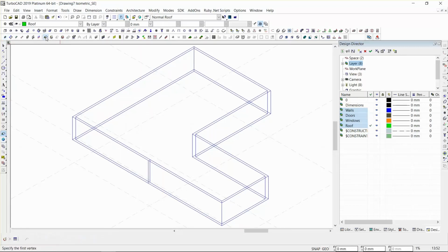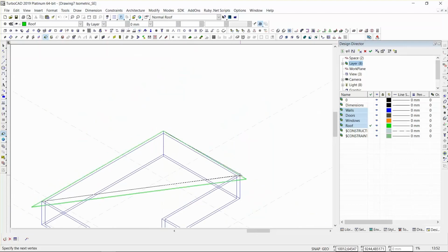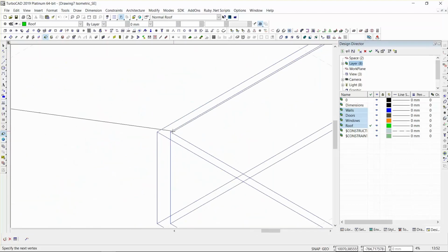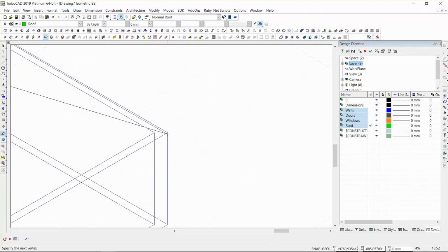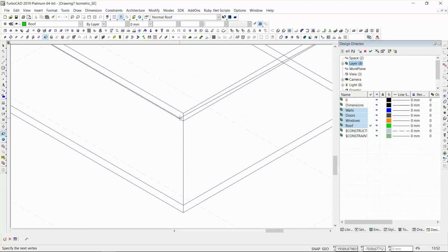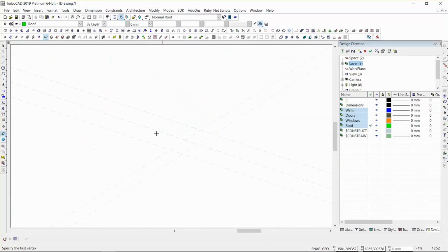That's why I showed you this other roof tool. Let's just go there. Right. I can connect the points exactly as I just did when creating the wall. Just take the outside points. If you take the inner points, your roof will go through your walls. Okay, see what it does. And finish. Look at that.